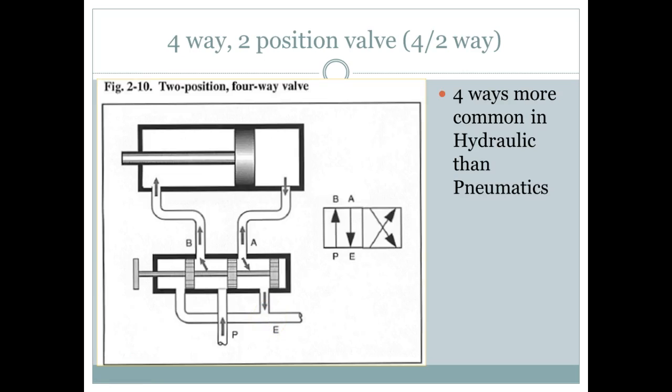Now, of course, what that does is the 2 positions don't have to share the exhaust port. And we're going to add a valve that's got 2 names before long. It's called a flow control valve, or some people call it a throttle valve. With the throttle valve we can set the speed of the flow.